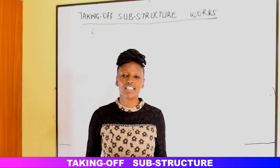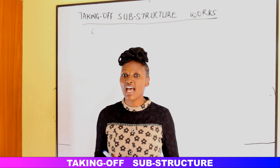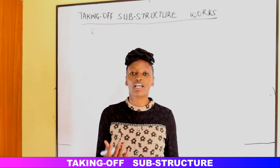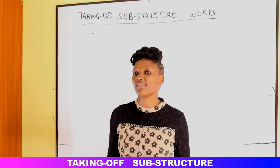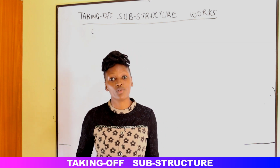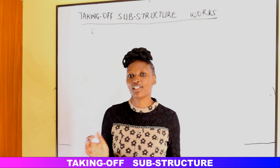If it says meter cubed, it's length times width times height. If it's a very thick floor, mass concrete in the floor, and it says meter cubed, then it's length times width times the thickness. So you just need to consult your method of measurement, especially where it talks about meters squared and meters cubed.